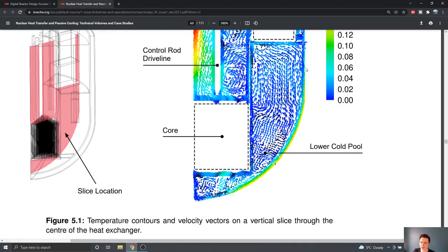This is the really interesting bit: this outer wall of the reactor here, of course, is connected by the gap to the outer surface, which is then cooled by the water pool. And so this region is really cold. It's got a cool boundary that's cooling it down. And what that does is it locally cools the flow, and that changes the density of the lead. So the lead gets cooler and its density changes, it gets a lot heavier, and then that drives the lead along the surface of the reactor vessel here. We have a sort of a negative density current.